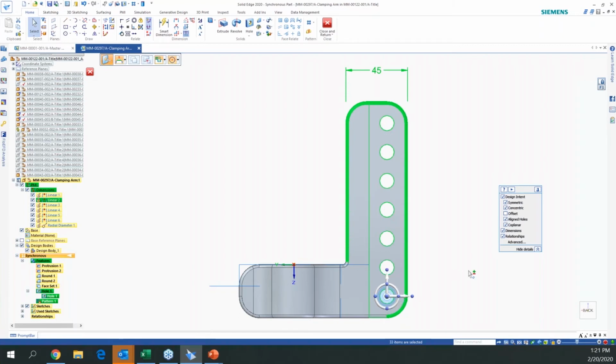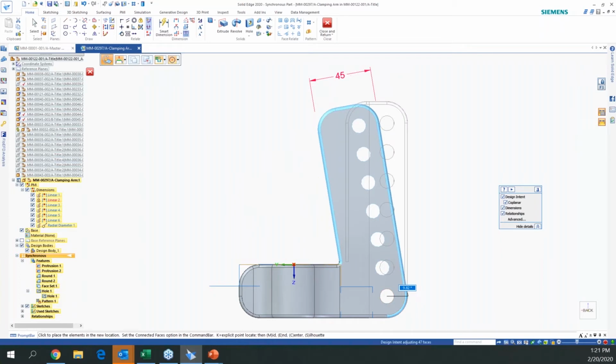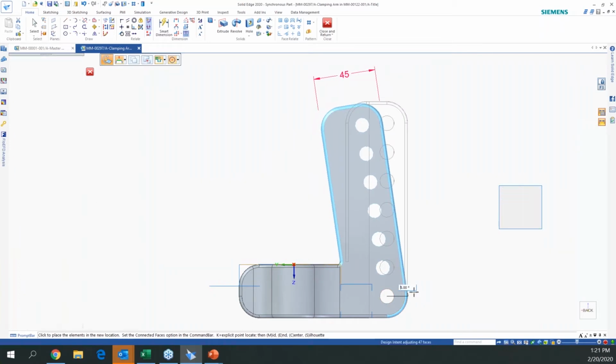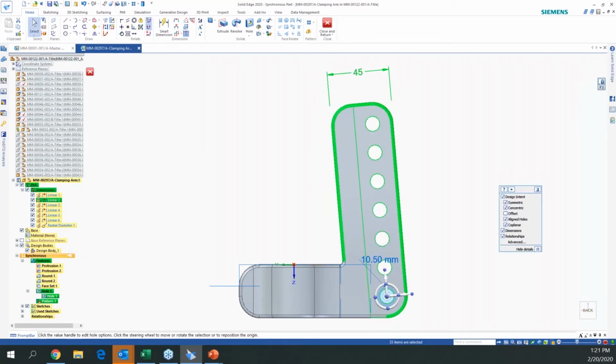So you can see I select the point. I selected actually the whole circle itself, and it snapped to the center point. Now if I take the steering wheel and just drag it a little bit, you can see here I'm just dragging it, and it's dynamic, and that's kind of a preview. But say I actually want a 5-degree angle on there. So I type in the 5-degree angle, and it gives it to me.